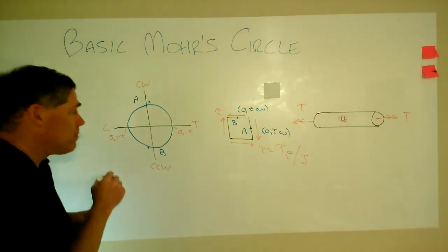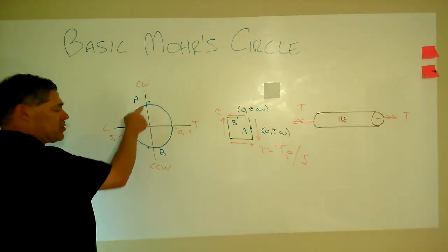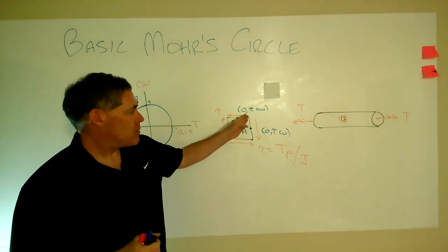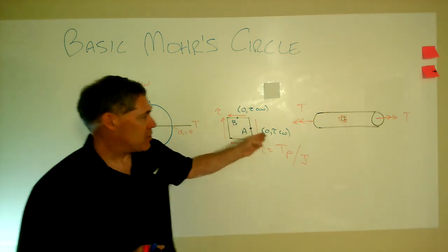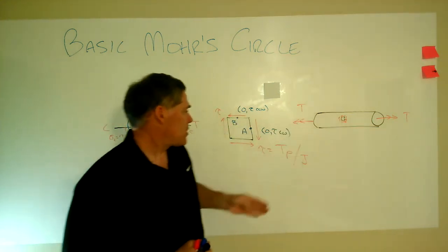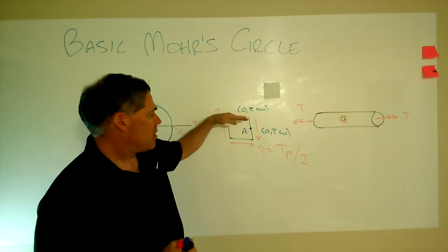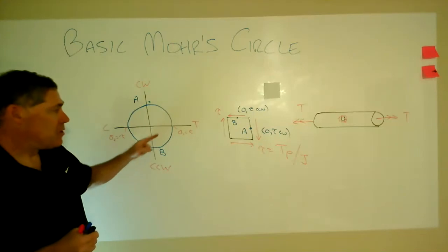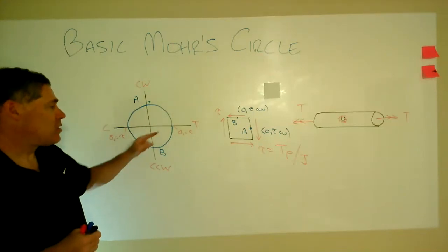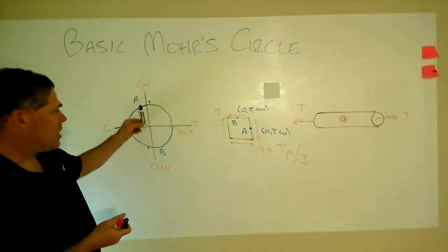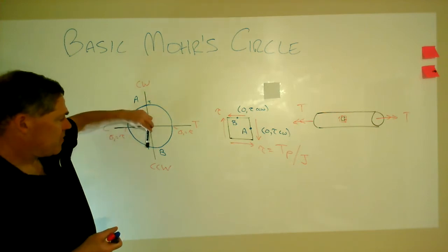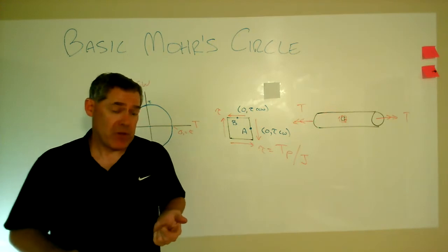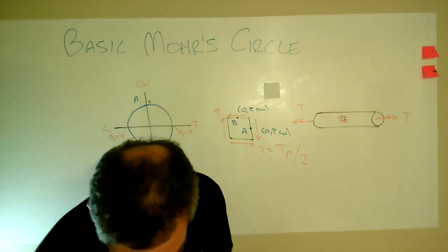That's really important. We have the maximum shear stresses on the top and bottom. So notice that shear-wise, we have our maximum on the cross section itself. A represents that slice through the body, and then there's also one at the horizontal layer. Pretty interesting there. But the maximum tension is happening on Mohr's circle at 90 degrees from the various maximums. That means in real life, at 45 degrees from those planes.